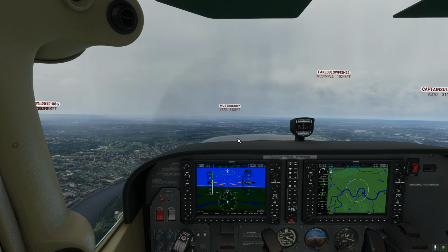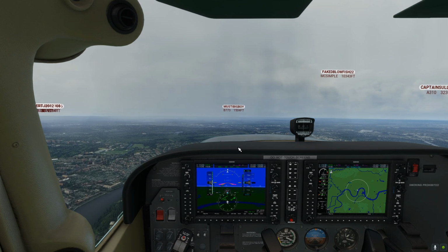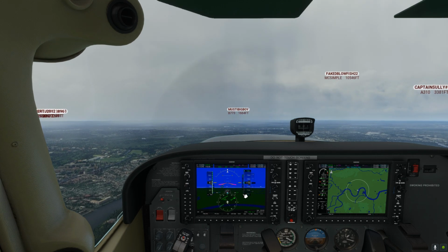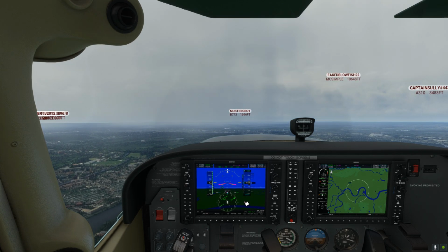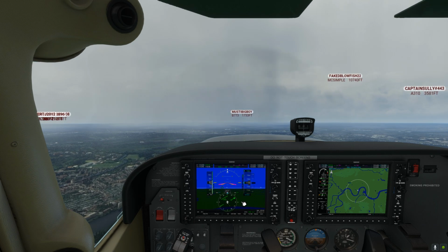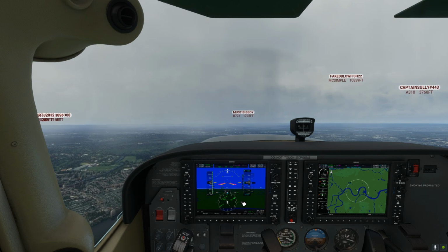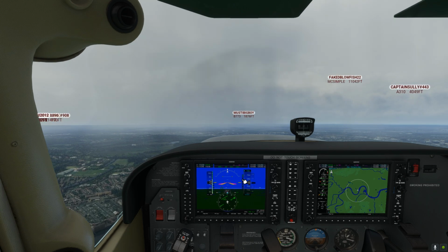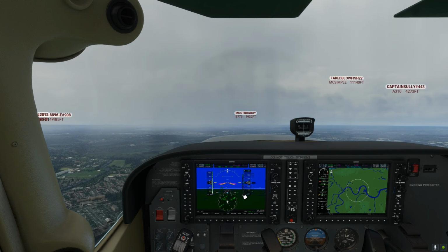High hopes for this, it will start to move in. And when it does, that's when I can press my approach button. So you can press it quite early, even before the glide slope indicator starts moving down.